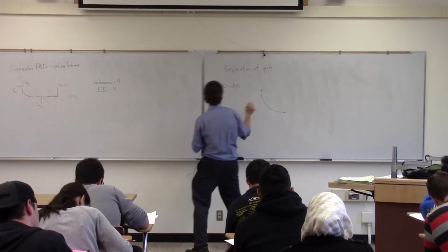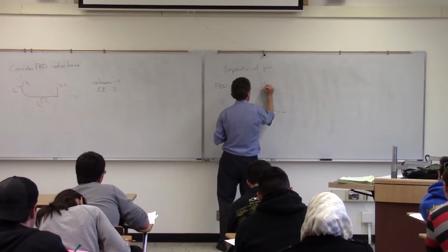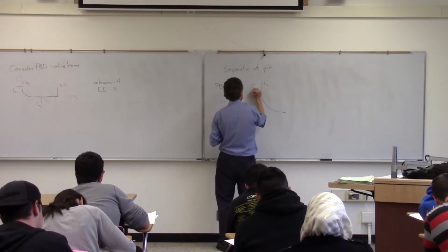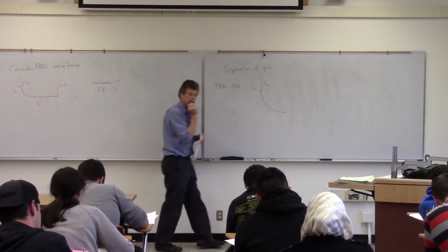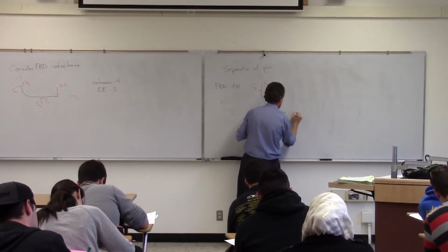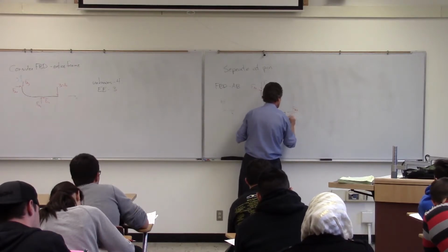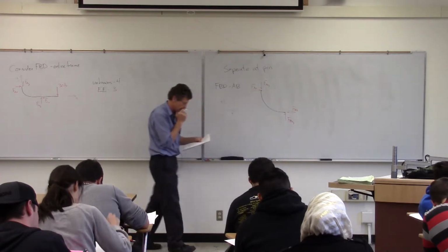That one. So that doesn't change. I mean, that's still a pin connection. But I've got a pin connection down here, and I can do the same thing because it's a pin connection. I know it's an unknown force and an unknown angle, so I'm going to draw it in terms of its two component forms.